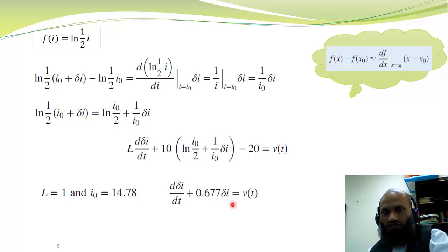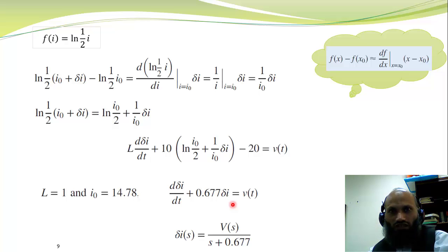We can even write it in the Laplace domain by taking the Laplace transform of this equation, and that is described by this equation. Remember that the transfer function can only be obtained for linear systems. For nonlinear systems, we do not talk about transfer functions. Here we have obtained a linear approximation to that mathematical model, and then we worked out the things in the Laplace domain to obtain the transfer function.